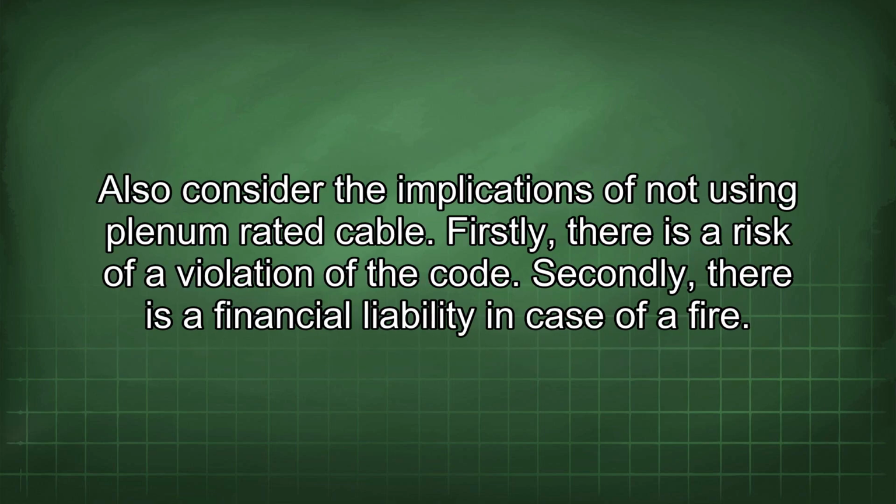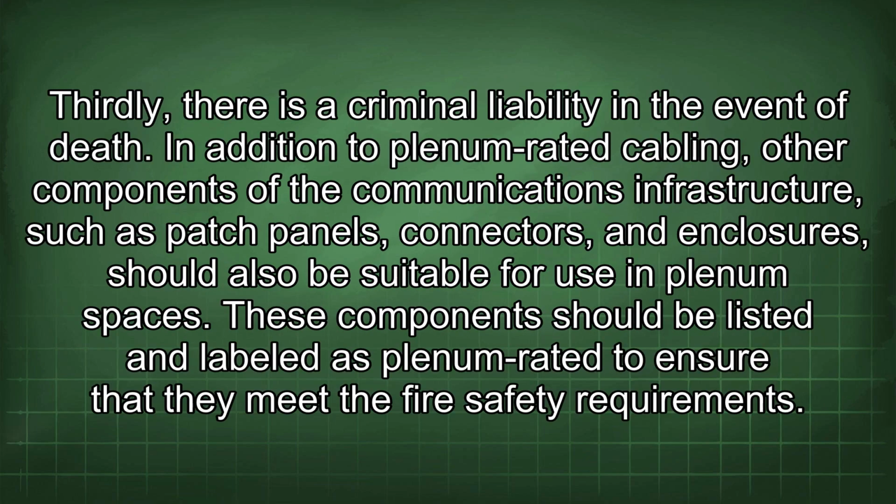Also consider the implications of not using plenum-rated cable. Firstly, there is a risk of a violation of the code. Secondly, there is a financial liability in case of a fire. Thirdly, there is a criminal liability in the event of death.